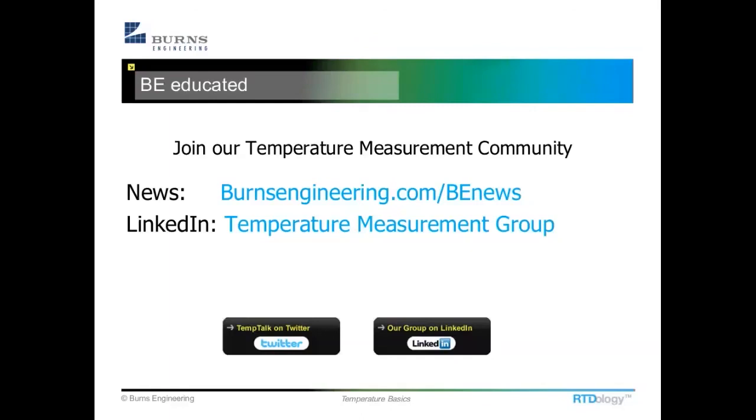My guess is that whatever the calibration point is, they don't want it to differ more than that 0.3 degrees C. Typically, it'd be a plus or minus number, though, and it's a little bit suspicious in that it's 0.03 and 0.3. It almost seems like there might be a typo. 0.03 would be really tight for an industrial grade PRT. 0.3 would be pretty realistic. I'd probably need a little more information to get the best answer. But it looks to me like they maybe misplaced the decimal point, unless it's for a temperature standard of some kind.